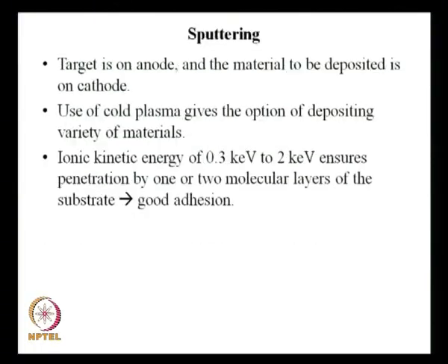So, if somebody wants to make a deposition to make an electrode at one particular portion on the channel wall, he has to resort to either thermal evaporation or the other technique, sputtering. Sputtering means instead of heat, you would be using plasma. That means you are providing the energy in the form of electron volts. So, these are the deposition techniques that we talked about.